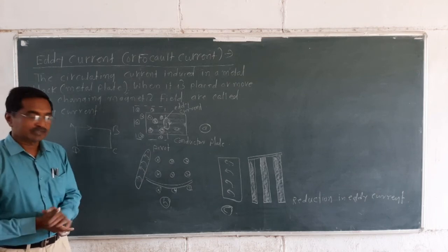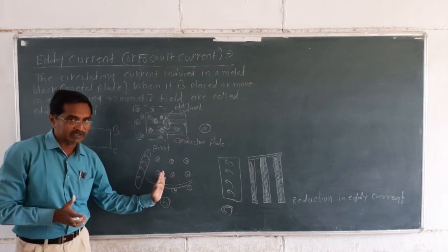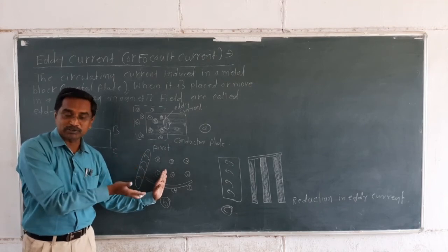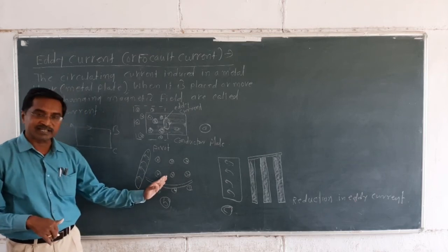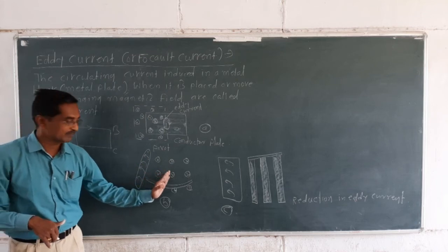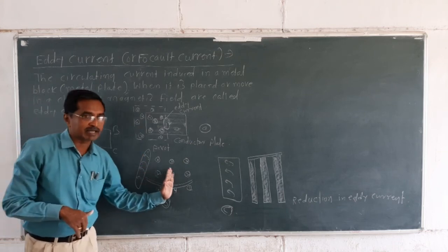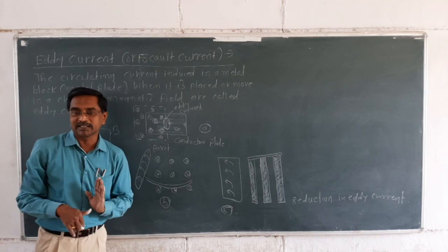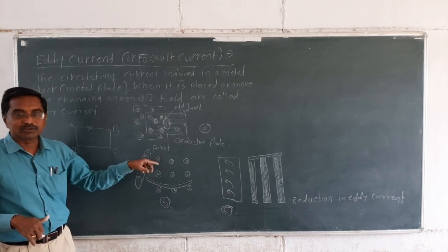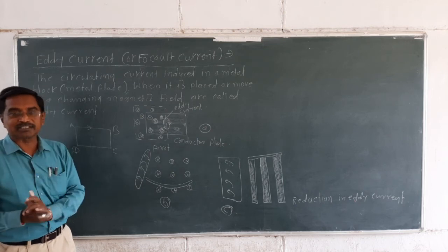Every swing, when the coil enters the magnetic field, an EMF is generated here, and that EMF opposes what produces the magnetic flux. So the EMF generated there will oppose. So when that metal plate enters or leaves the magnetic field, at that time the mechanical energy gets converted into induction, and finally into heat.